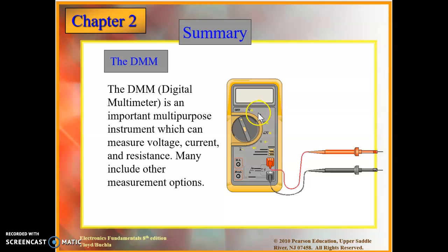In the case of measuring voltage, the multimeter represents a huge, infinite resistor, so when you make the measurement, you only put the leads parallel to the component you're trying to read, and it gives you the value of that component.